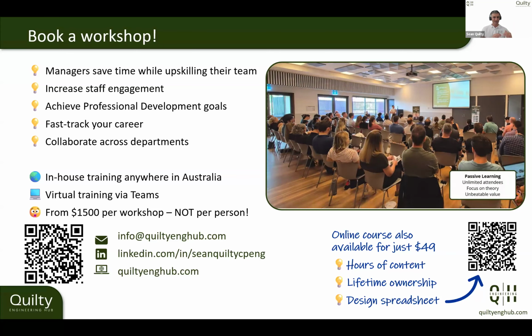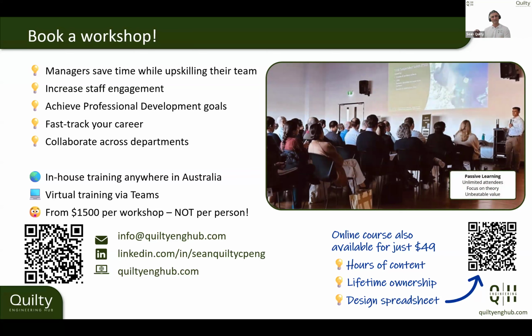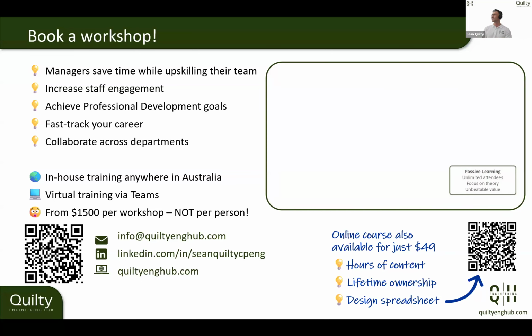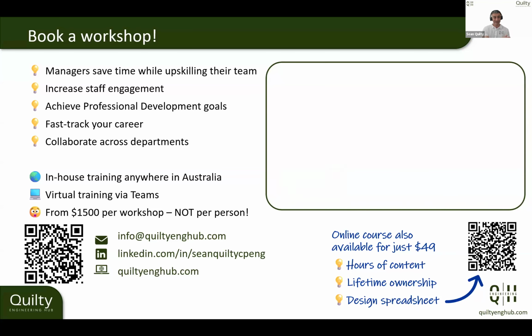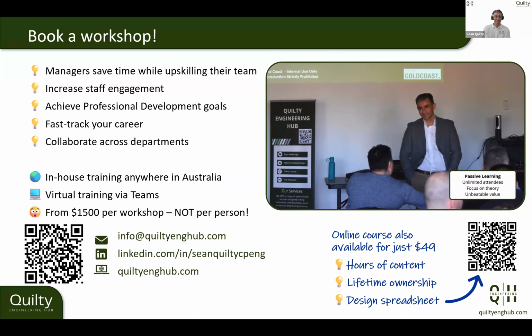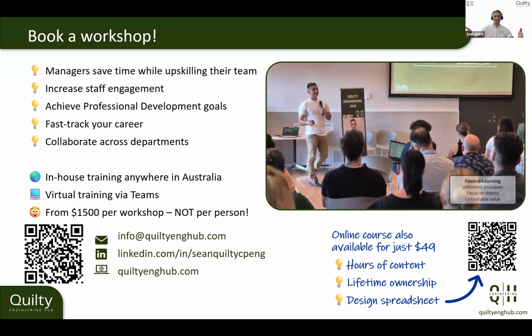So there's a few different ways to calculate the freeboard, but when to use the freeboard comes down to risk. If I'm looking at water running through a spoon drain that's only like 40 mil deep and it's just taking water off of the car park, I wouldn't use freeboard. You don't need to incorporate freeboard there, because if it goes outside of that drain, it's just going to hit your car park surface, no problem.